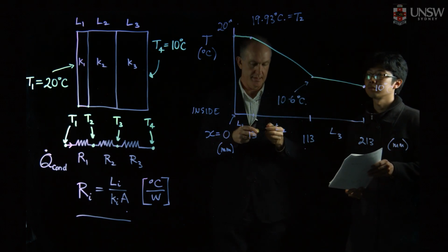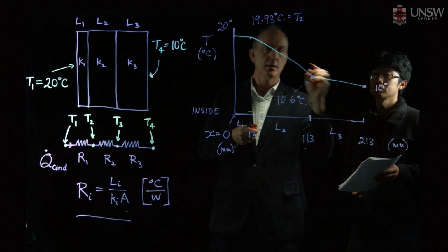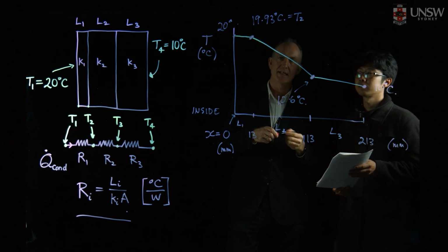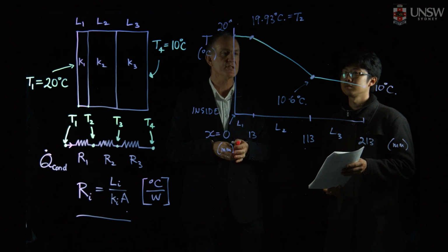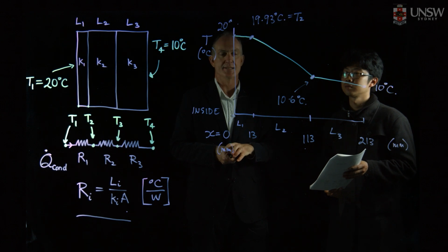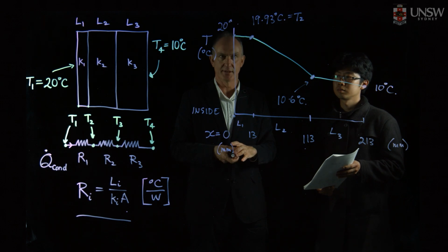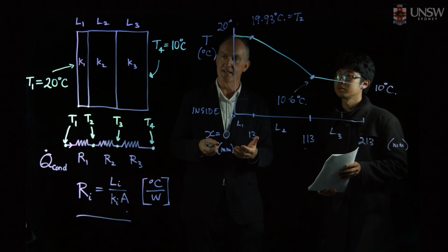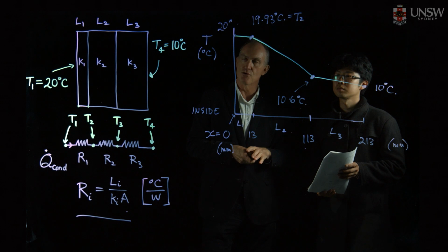And so if we draw the line now, joining up those points, make those points a little bit bigger, we can see, as we would expect, that for steady state heat transfer, most of the temperature change is across the layer in the wall that has the highest thermal resistance. So that makes sense. It's the one that gives the most resistance to heat flow, so most of the temperature drop occurs across that. The other layers, the more thermally conductive layers, particularly the thinner gyprock layer, less temperature drop across that.